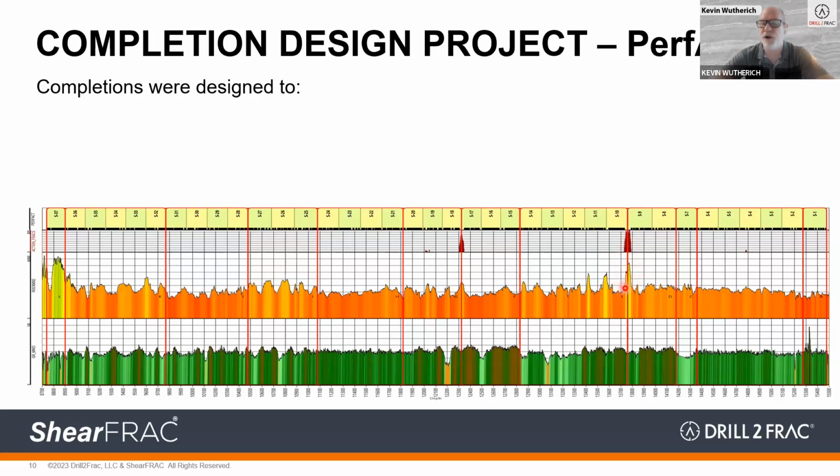One of the easiest things to do, especially if you have a well-defined area of depletion, is this: you can see that there's a very high rock MSE here, probably related to quite a bit of depletion. In that case, what we did is we put a stage boundary right there, and that just gives us a little bit of extra room to avoid putting a cluster right there. So we segment the well up to make those stage breaks so that they not only straddle these areas of localized depletion, but we also look for changes in rock type. You can see that the gamma ray and the rock MSE are changing quite significantly as they get into this new zone. So why not just put a stage break there so you don't have one stage straddling two different rock types?